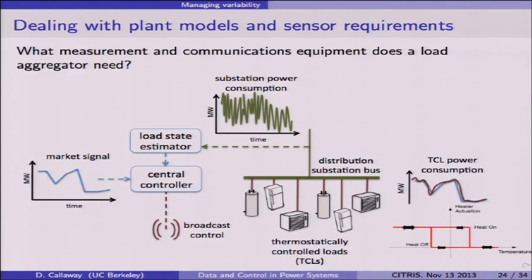One reason is that the SCADA equipment is there. Another reason is that smart meters, advanced metering infrastructure, are very good at listening to information. As some of you may know, they're terrible at quickly, at least, sending information up to some sort of central place. But they're, in some cases at least, very good at receiving broadcasted information. So this is a mechanism that we could use where we've already got smart meters, we've already got distribution substation SCADA. We really just have to broadcast information and then have some local control infrastructure. So it's potentially the least cost, at least in terms of infrastructure, way of getting to some sort of a workable demand response scenario.